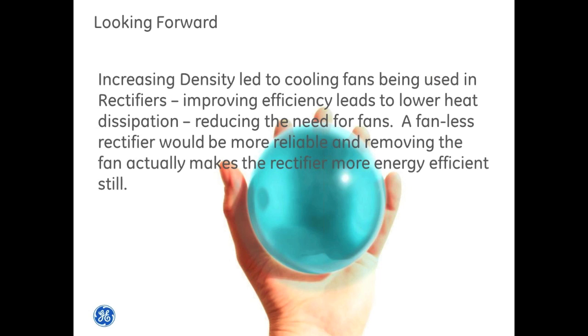We'll reach a point very soon where the efficiency of the rectifier is high enough that we don't need the fan to move air through to get rid of the heat. This in itself will add another layer of improved efficiency because the fan consumes some power itself. So not having a fan will inherently make the rectifier more efficient. It will also make it more reliable. One of the first things to fail in today's switch mode rectifiers is typically the fan, and in some cases they're user replaceable. But as costs have come down, that's less and less the case.